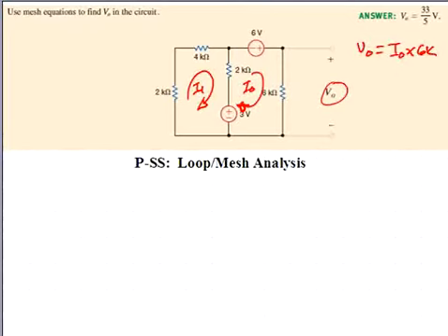As we recall, in doing the mesh analysis, we'll be applying Kirchhoff's voltage law and summing voltage drops around the loops or meshes. We'll label the polarities of those voltage drops around these loops, obeying the passive sign convention for the indicated loop currents.